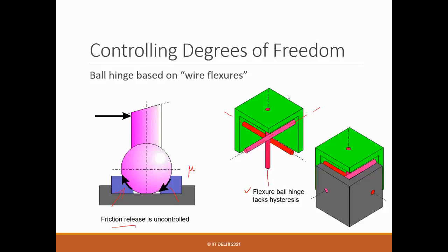Of course, what you have to understand here is the 3 points, the middle points, are not intersecting here, and they are moving also, but very much they are deterministic, and you can calculate beforehand how much they will deviate, and you can always compensate for that. What is good about it is you don't have a hysteresis, because if you apply a force, there will be deflection.